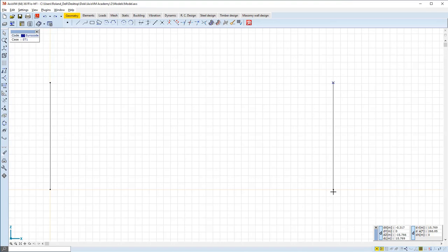Okay, so with that out of the way, let's use some polar coordinate input to define the vectors of the beams of the frames. Cylindrical and spherical polar coordinate inputs are available, cylindrical being the default, so we need to input the radius by pressing R on the keyboard and giving a length, and the angle by pressing A and giving the pitch for the vector.